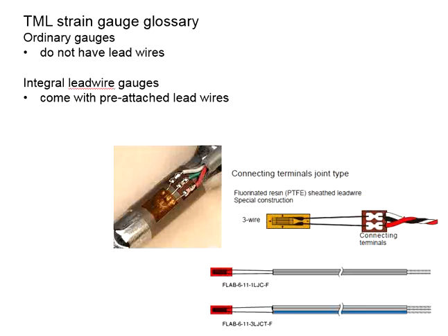Now, how do you connect the wire with the strain gauge? You will need a connecting terminal, which looks something like this. Solder the gauge lead onto the connecting terminal at one end, and then solder the wire on the other end of the terminal so that the current can pass through the wire to the strain gauge and then go back. This completes a circuit, and then later this wire is connected to the data logger.